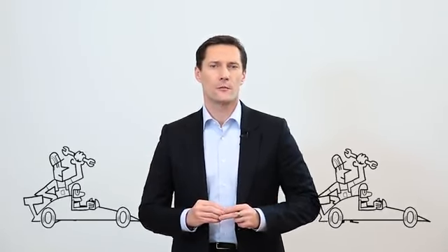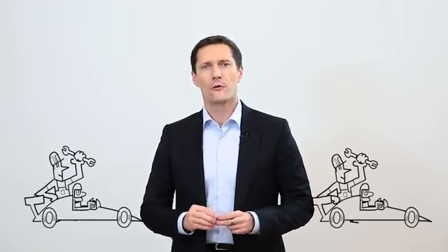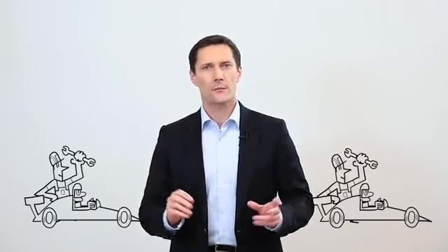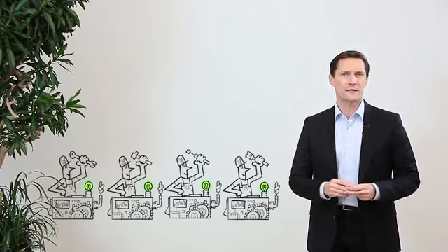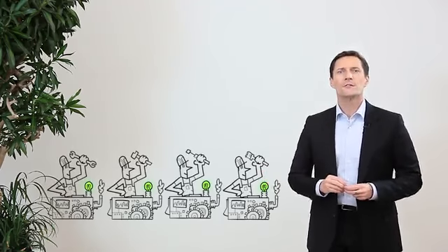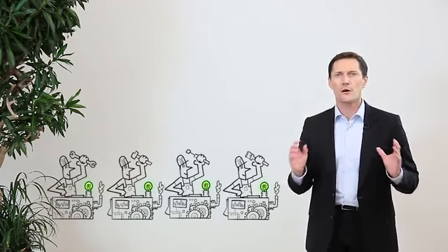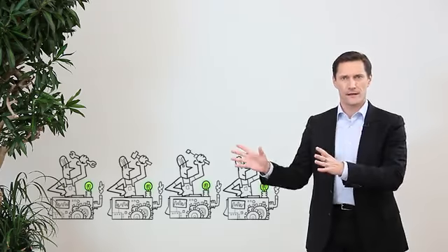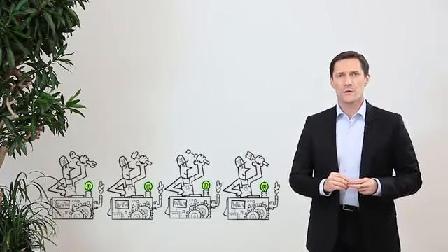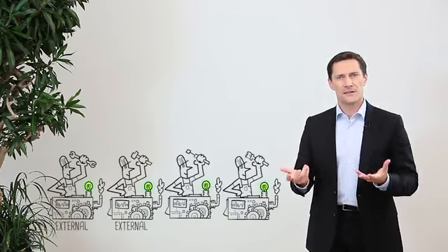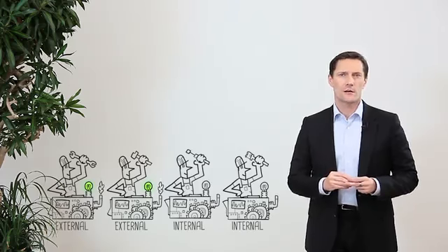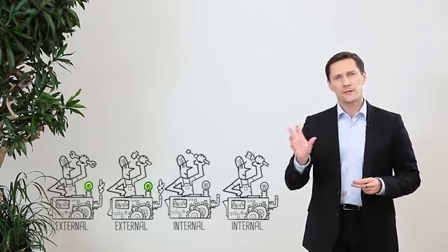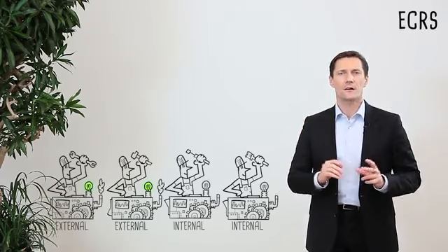You can compare the approach like a well-organized pit stop in Formula 1. The whole team follows clear standards where work is optimized and parallelized. It looks complex, but SMED is very easy to apply. First, you need to observe the process and capture all process steps from the beginning to the end. Then you distinguish between external tasks that can be done with the machine running from internal tasks that require shutdown of the machine.